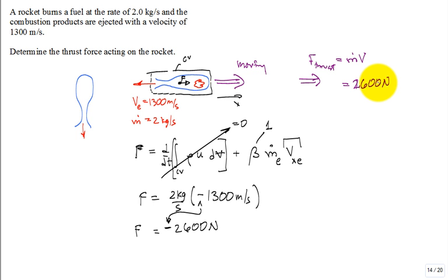It's one of these perspectives. I have a rocket, it starts burning, it starts throwing out fuel out the back end. It's bolted to the bottom of a wing or whatever it's bolted to, if it's a jet engine or something in a model airplane, it's going to push that object forward with a forward thrust. If I want to not let that rocket move anywhere, I'm going to have to apply a force to counteract that forward thrust and push it back or hold it stationary. And that's what we're calculating for, is to hold it in place. Basically, I calculate the force to hold it in place, turn it around and call that thrust. That's right.